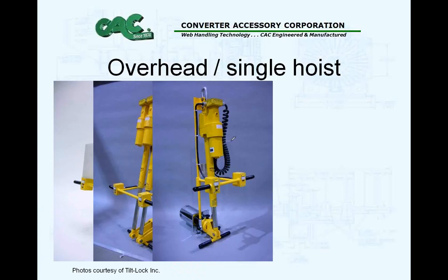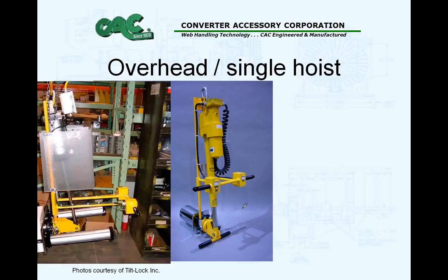Again, a similar system, but this one is for a 6-inch core. You can see that's a bigger probe designed for bigger cores, for 6-inch cores. So generally, these systems can be designed for cores up to about 18 or 20 inches in diameter, and all the way down to 1-inch diameter. So there's quite a bit to choose from. Most people run 3- and 6-inch cores, but if you have odd-sized cores, probes can be designed for that.